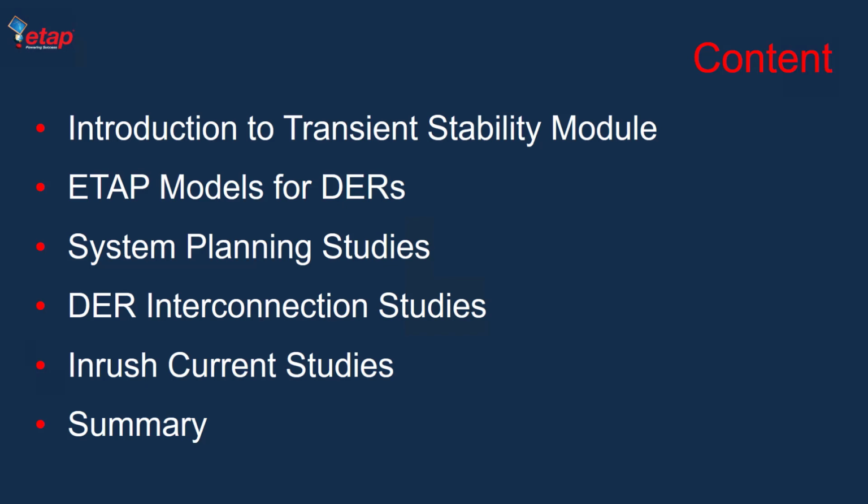As part of ETAP 20, a new feature recently released allows you to simulate inrush current within transient stability analysis with good accuracy. This approach is good enough for many designs and protection settings applications. We will have a quick demo of this feature and how it can be used to evaluate the effectiveness of pre-magnetizing a transformer to reduce inrush current. In this webinar, we also use the new plot view, a new feature in ETAP 20, throughout all the demonstrations. Finally, I will summarize this webinar.